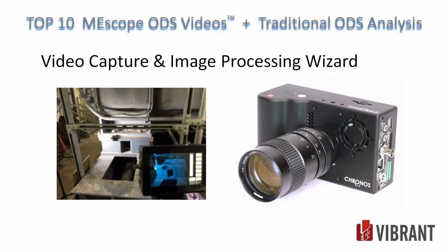But what I also do is I usually take an accelerometer measurement. Like here, on this unit, this was the turbine generator. I took bearing measurements. Oh, we're not seeing it. But then just to quantify, am I in the ballpark of my ODS? Yes, I am. I'll get that frequency. I can convert it with the signal processing parameters to velocity and peak to peak or peak, whatever you want to use as far as amplitude, and you can correlate your data.